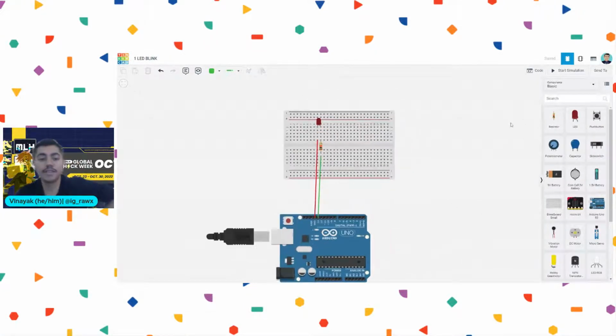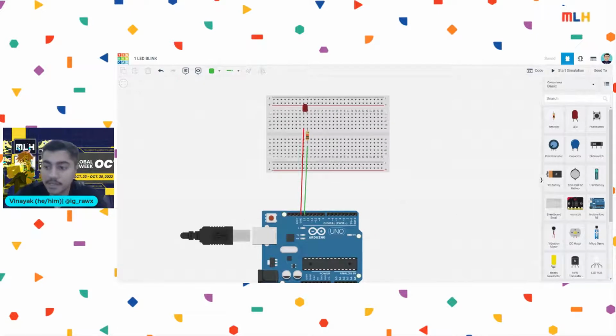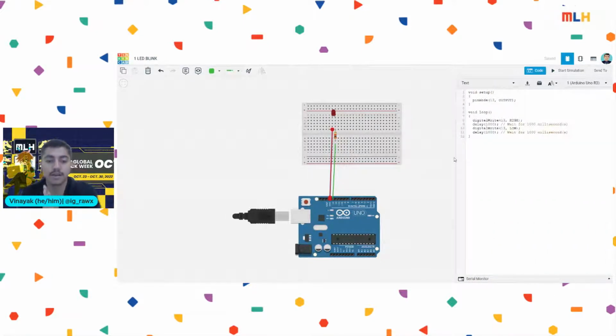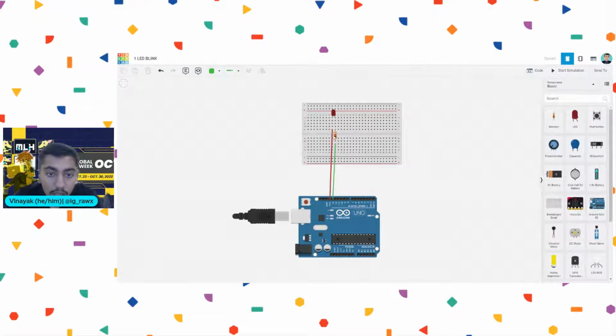Okay, this is the best way to understand this. We have a proper Arduino, a simple Arduino, a resistor, a proper LED, wires, and a breadboard. When we talk about the code, you can clearly see the negative part has been connected to the ground. The resistor part for the anode is connected to 13. And when we talk about the code,